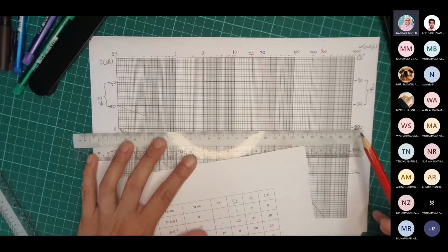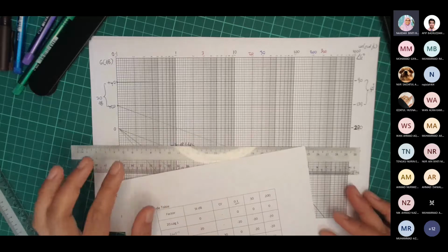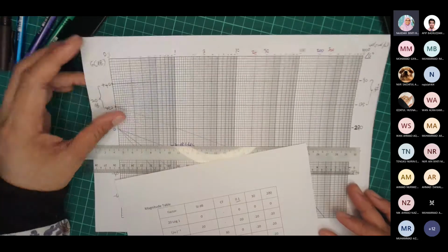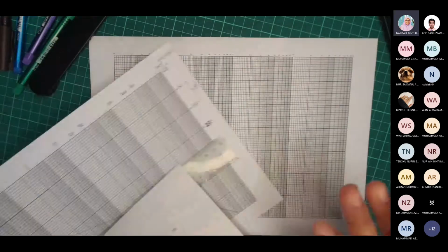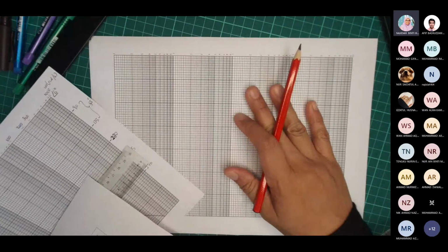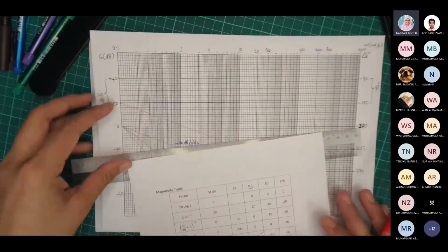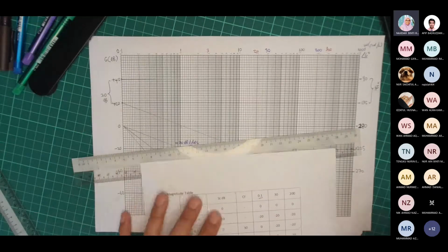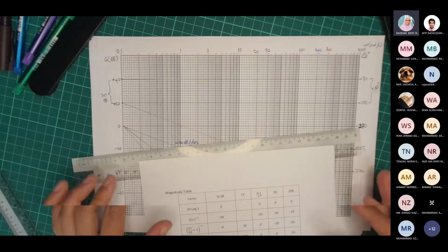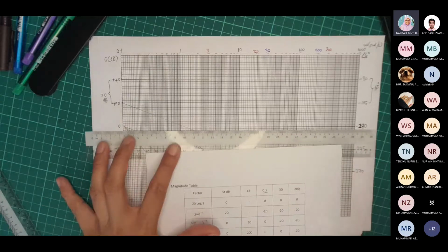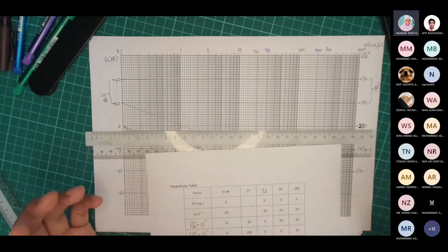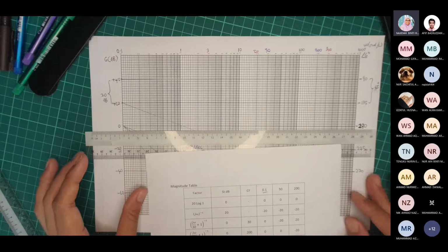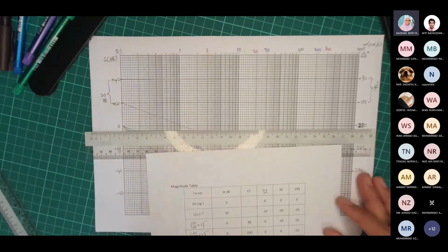It is not necessary, because there are some other people who would like to sketch the magnitude plot on one graph paper and the phase plot on another graph paper. So 0 dB and -180° are not in one line, even on separate semi-log graph paper. That's okay. In my case, I suggest to my student just use one semi-log graph paper, and plot both magnitude and phase together in one paper.